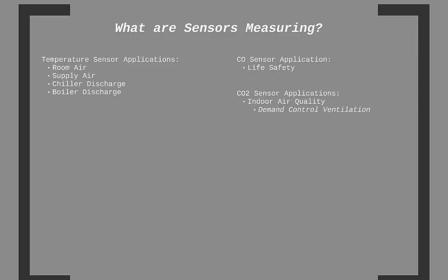Smoke sensors are also used for life safety purposes. When the presence of smoke is identified, a signal is usually sent to initiate an alarm to alert occupants. Additionally, such a presence of smoke in the ductwork system could be used to initiate a control sequence in the air handling system to allow for safe exit of occupants, for starving the fire of oxygen, or at a minimum, just shutting down the system to prevent the spread of smoke to other locations in the building.